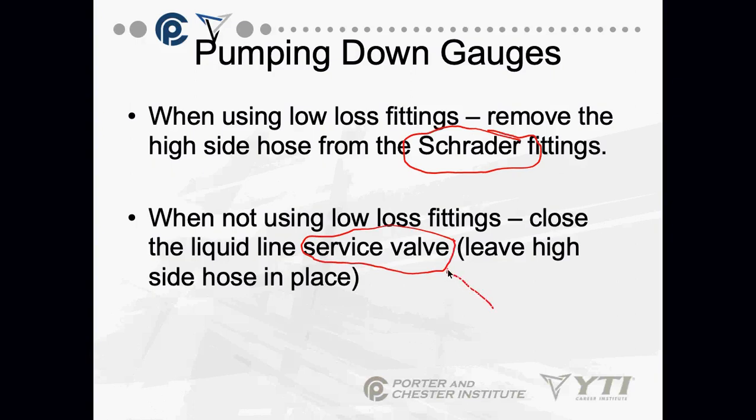A service valve is basically a valve you open and close with a wrench. That is more used in refrigeration. In air conditioning, more often than not, you're going to see Schrader valves. Again, they look like bicycle or car tire air fittings, with a core that presses down, and when the core presses down, it gives access to the refrigeration system.